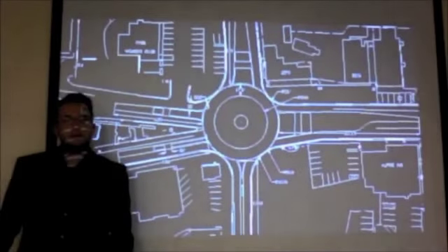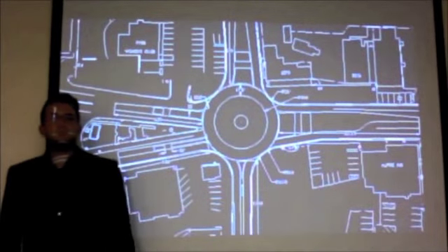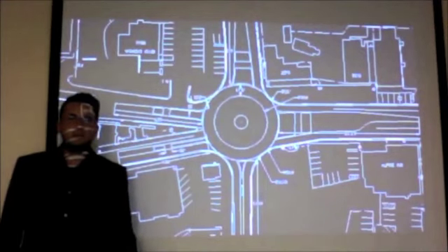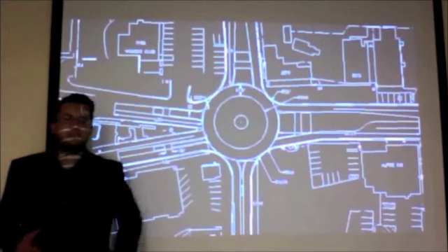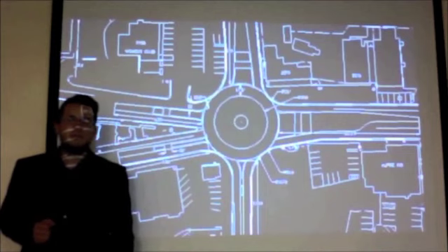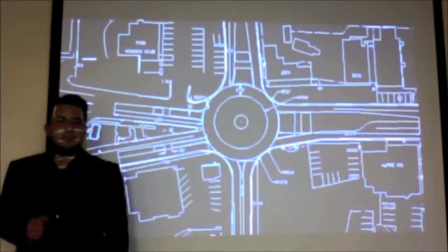By using a roundabout, the safety of the intersection is improved while making the flow of traffic more constant, since they don't have to wait for the traffic light to turn green. A roundabout is safer since vehicles have to go around the circle at lower speeds. Also, the decision making is simplified since it is a yield upon entry.